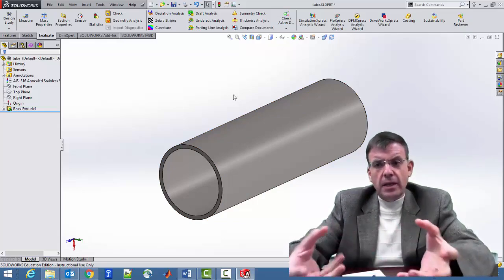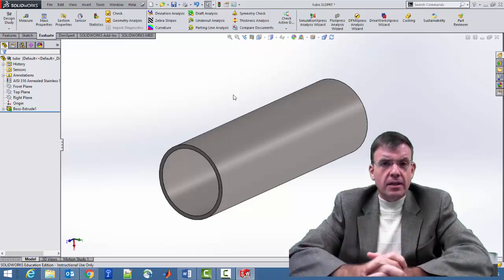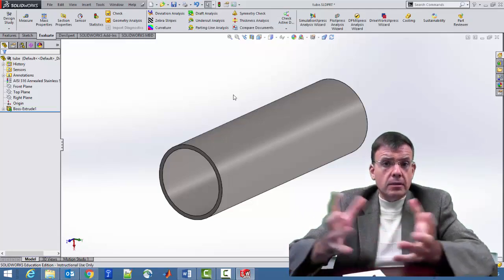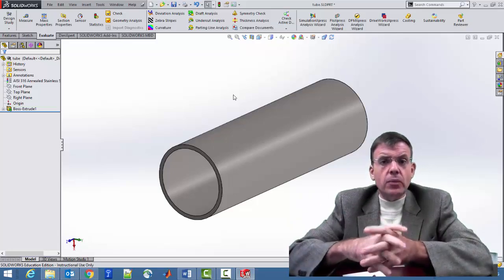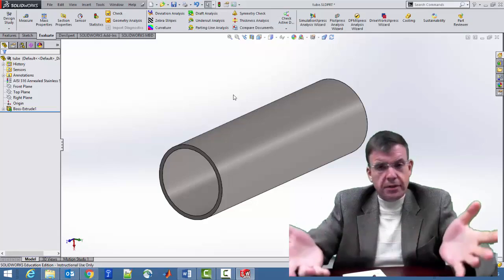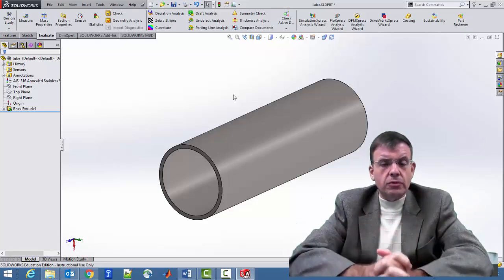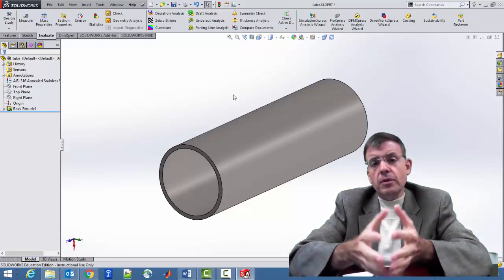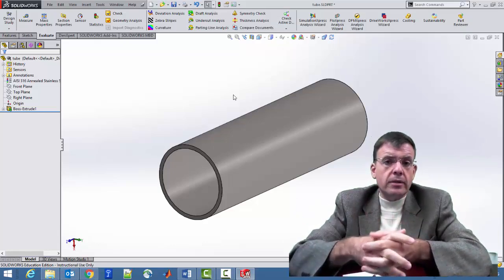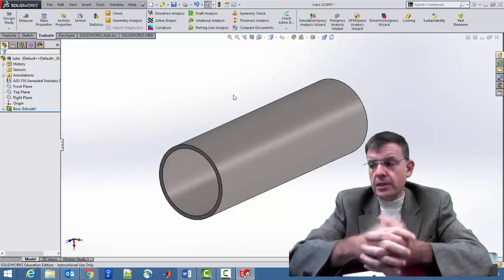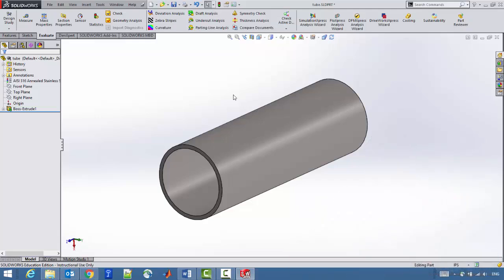So just if you had a hot object sitting in still air, it would convect heat to its environment at the rate of approximately, and it's a very rough number but useful for our purposes, 20 watts per meter squared degree Kelvin or degree centigrade, either way.